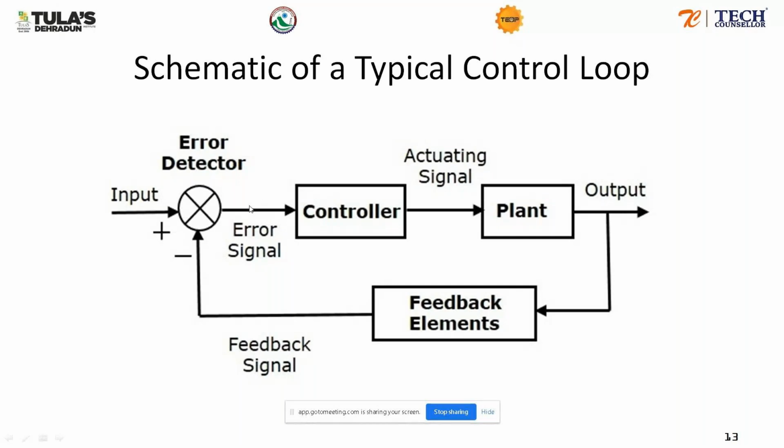This will be that chip, something like that. And then the controller will analyze it. That error should have been 0. That's what we want. We want the temperature to be 25. So in an ideal case, input is 25, feedback is also telling 25, error is 0. But the controller senses that error is not 0, it's minus 7.